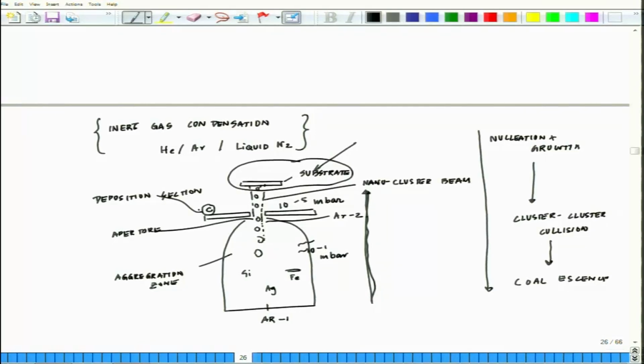An EBE system consists of a vacuum unit, an electron beam source and target material. Again you see, you have a vacuum unit out here, as I showed you, the aggregation zone, which is a vacuum unit. Then you have the electron source, and then you have a deposition ground. So, the way it works is very simple. The electron beam hits the target material. The target material atoms evaporate when the temperature reaches above its boiling point, and the evaporated material is then transported and condensed on the